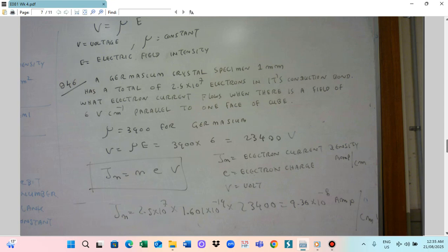In the meantime, electric charge is also accumulated on the surface. The surface integral of D dot dS equals the summation of Q. When you are closer to the charge, the potential will be higher. The potential difference can be calculated as V1 minus V2 equals the negative integration of E dr. When a static field is impressed, the capacitor will retain a charge, and the capacitance will be Q divided by V.